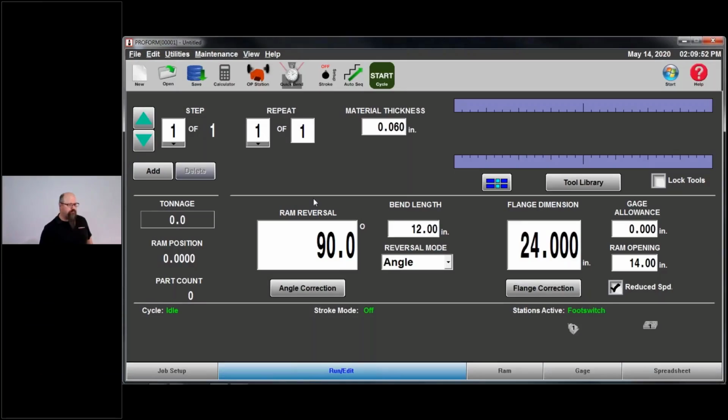If I'm making an upward bend, I should not have my hand over the part like this. But if I do that and the part comes up and I have that 1 inch default, then I didn't lose my actual finger or fingers in that instance. So that's probably why that's at 1 inch. You can set it to anything you feel is safe.